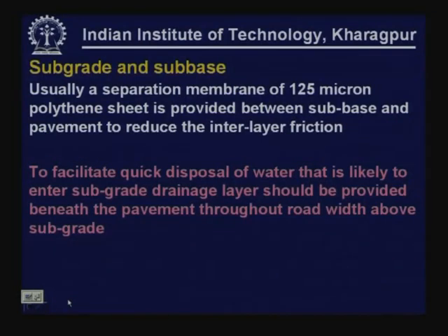Also, to facilitate quick disposal of water that is likely to enter the subgrade, a drainage layer should be provided beneath the pavement throughout the road width above the subgrade. If there is a significant requirement of drainage, a drainage layer over subgrade can be provided.